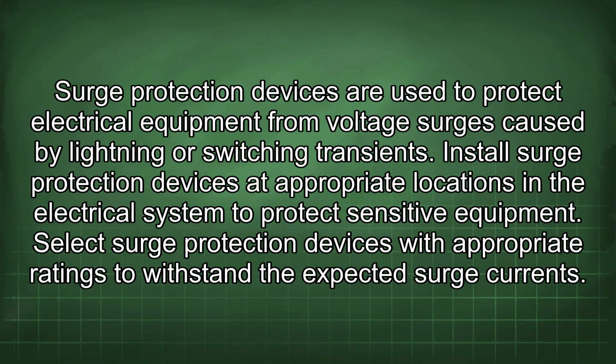Surge protection devices are used to protect electrical equipment from voltage surges caused by lightning or switching transients. Install surge protection devices at appropriate locations in the electrical system to protect sensitive equipment. Select surge protection devices with appropriate ratings to withstand the expected surge currents.